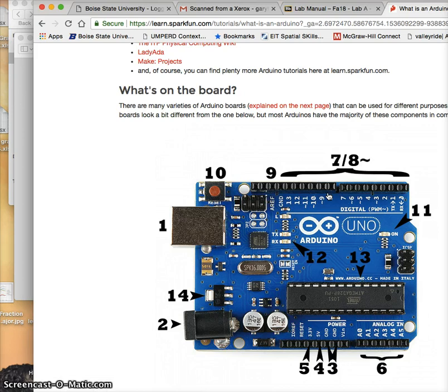So in our previous example, we would have to have our inputs attached to a couple of pins, and our headlamp would be attached to a different pin. For the lab we're going to do this week, we're going to use output pin 13. So we'll have to make 13 be an output. The advantage of using pin 13 is that pin 13 is also attached to this little LED right here. So if 13 is high, this LED will be high. If 13 is low, this LED will be off.